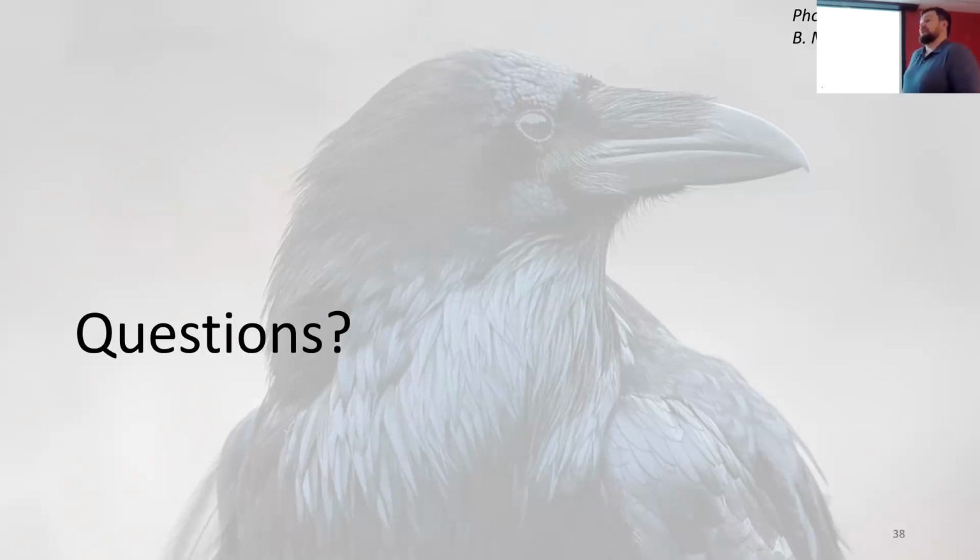So yeah, I probably use the terms probability and likelihood as being interchangeable. But what I'm talking about is we're trying to assess things that can only be described probabilistically, right? The 100-year flow is a statistical definition. It's a frequentist definition that if we have an infinite number of years of data, we can describe perfectly. The uncertainty is in that probability estimate because we don't have 100,000 years of data or correct model output in order to infer that value.